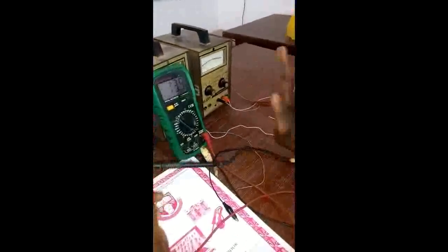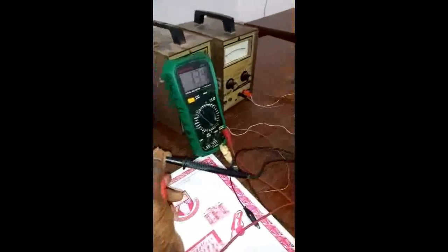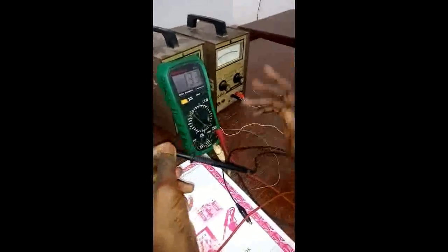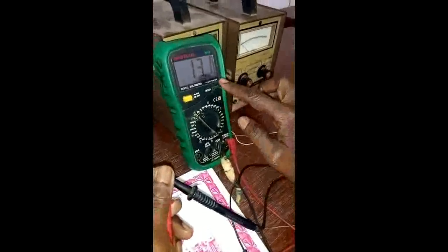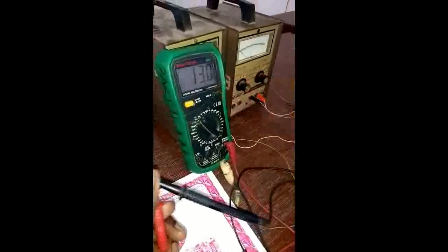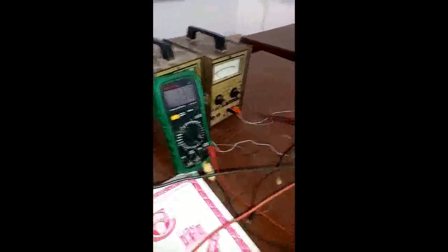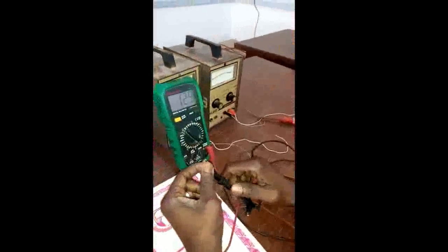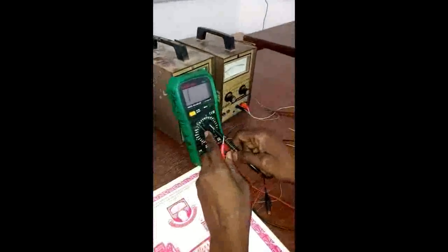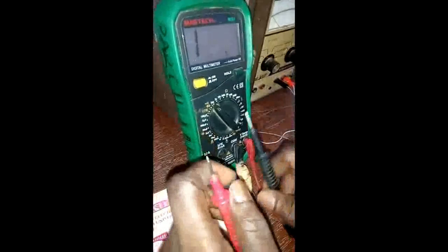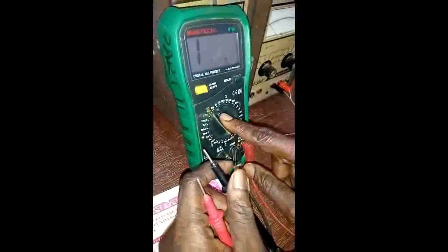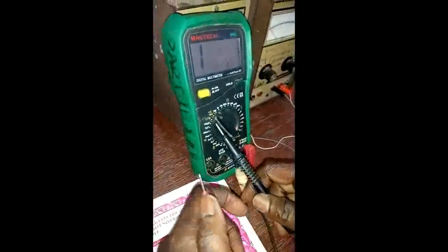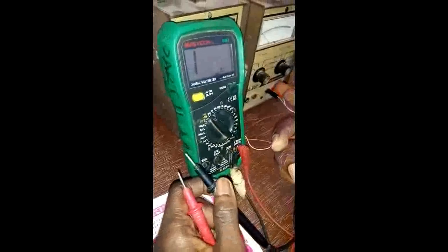So normally, it is supposed to give you around 0 or thereabout. But maybe because the battery inside is not working perfectly, that's why you are seeing this as high as 30. Or maybe the resistance of this one is almost close to that one. Now, if you want to measure any resistance value between 0 and 200 ohms, you select this one. Anytime you have anything greater than 200 and you select this range, it will never work. It will just give you 1 as well.